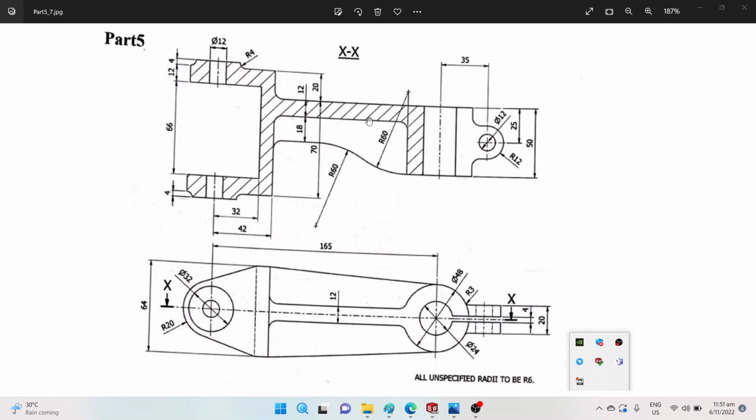All right. So how would you choose the datum plane? Simply, you do it by observing how the dimensions are being done. As you can see over here, you will realize that a lot of dimensions are dimensioned with respect to this line here. Okay, so from this line to the top surface is 20, from this line to the bottom is 72. And you'll also notice that a lot of dimensions are dimensioned from the axis of this hole, this circle. So naturally, I would want to use my top plane as the datum for this surface.